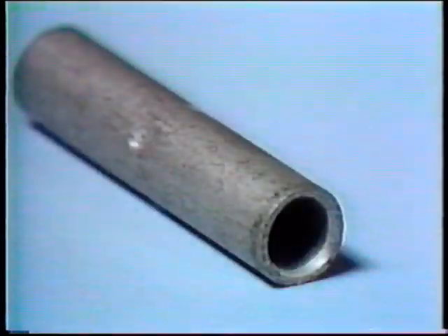For example, you might see the letters AL, CU stamped on the connector. This would tell you that the device was suitable for a conductor that was made of either copper or aluminum. The designation of AL stands for aluminum and indicates that the connector should only be used on aluminum conductors. Anytime you come across a device that has no metal designation on it, restrict its use to copper conductors.